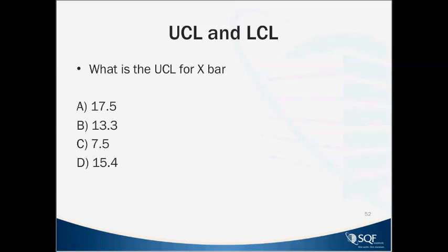Typically, we're trying to drive weight out so that we don't give it away, because overweights are a common cost issue in food. So yes, you have to change something in your process to either shift the mean or shrink the variation. Control charts, as we're doing here, I think, are the best tool to continually monitor and use the information. I'll show you a control chart in a minute.